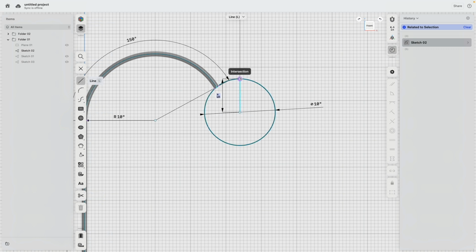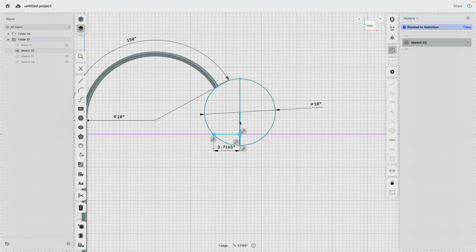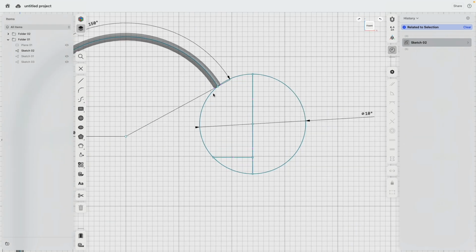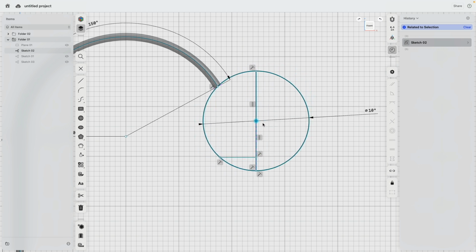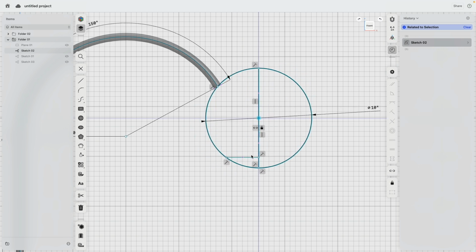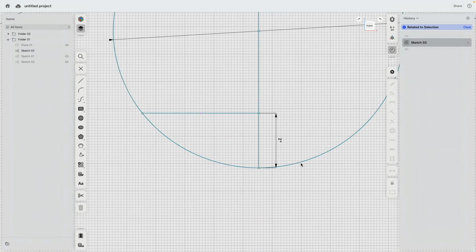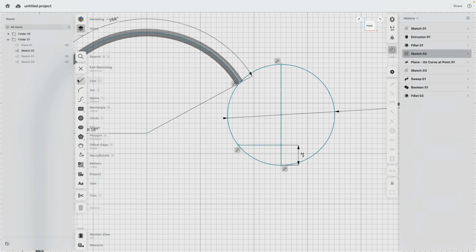Then to build this lampshade, I'm going to draw two vertical lines and then here one horizontal line. So these lines are horizontally and vertically constrained. Very good. And now you can see I can still move this around a little bit. And we can specify, for example, what's the distance here? 2 inches. Okay, that then specifies the width and the length of this line.